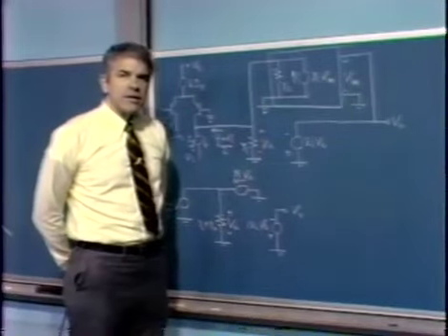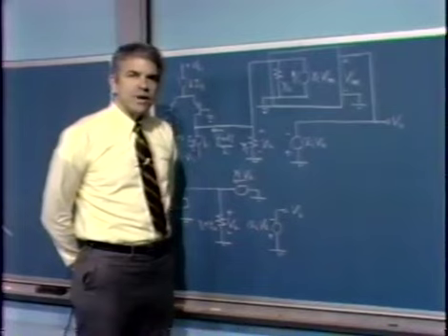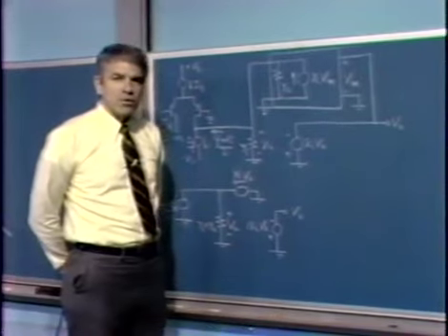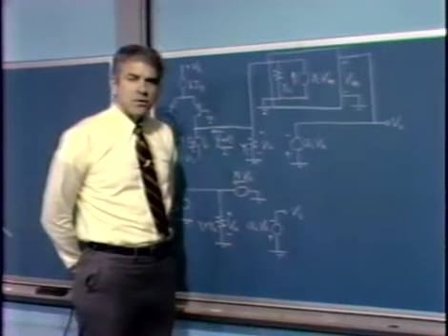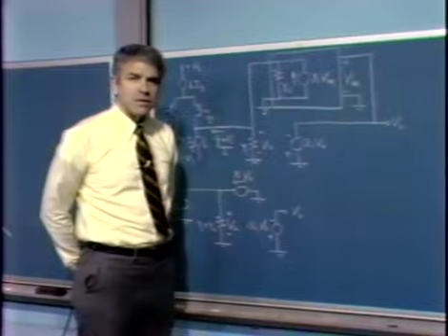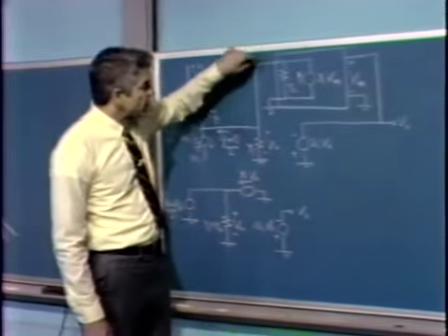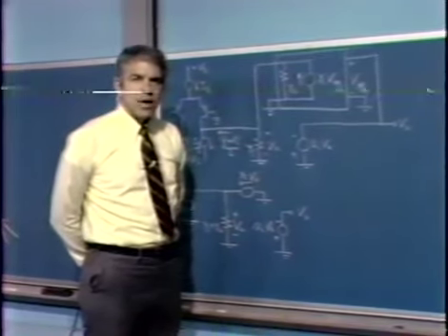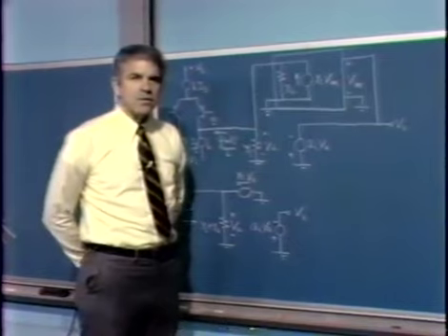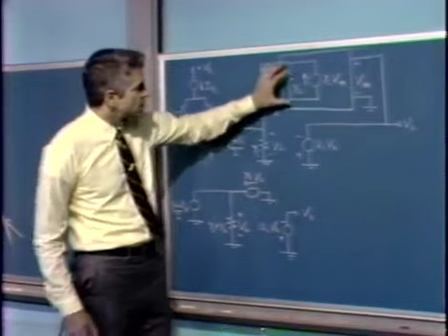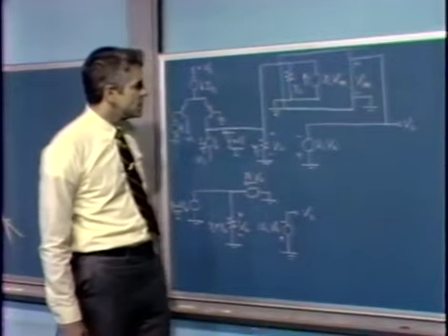Let me point out that my convention here is a little bit at variance with standard two-port convention, and I've chosen to do that simply to save some minus signs in the development. The usual convention defines currents in a two-port as being into the network. The way I've defined my short-circuit transfer admittance is considering the current out of the network. My reason for doing that is just that it saves some minus signs in the development and hopefully some confusion. I've always found that I work a little bit better with fewer minus signs, so that's the reason for violating standard conventions in this development.